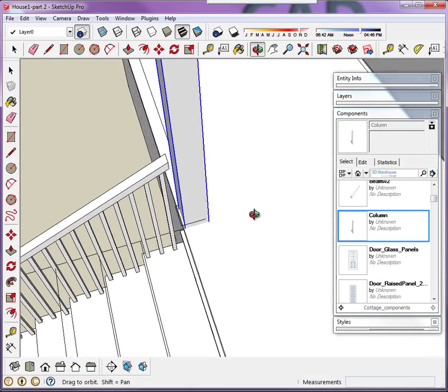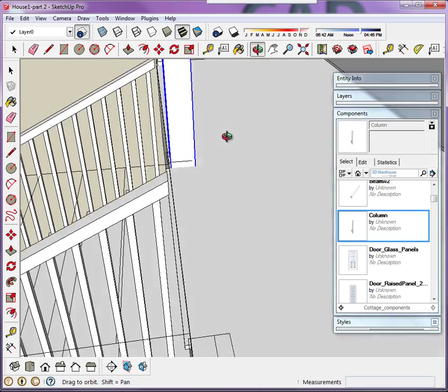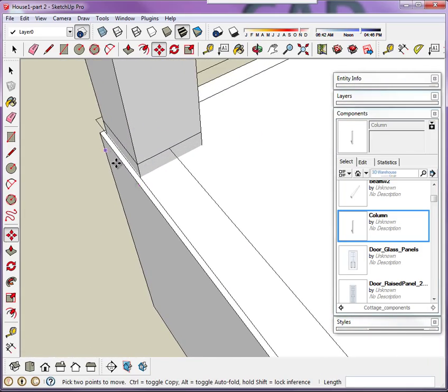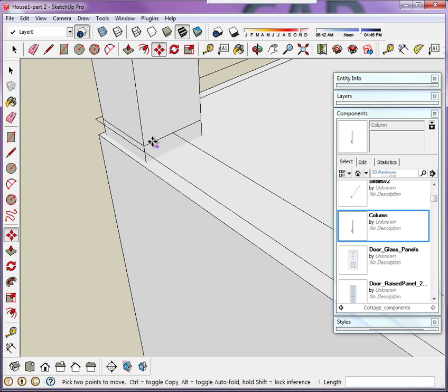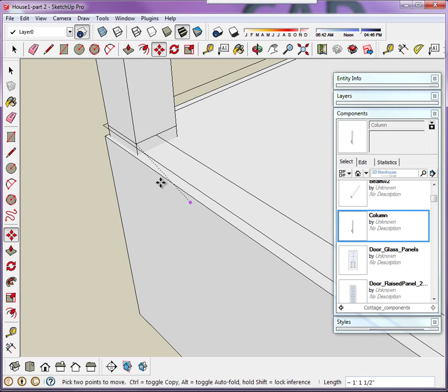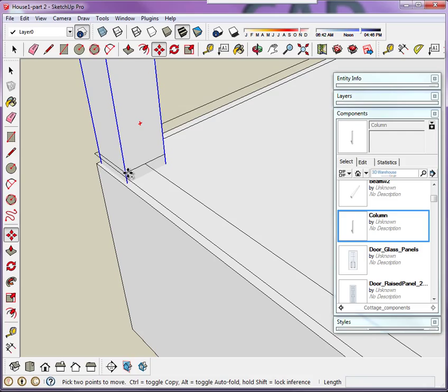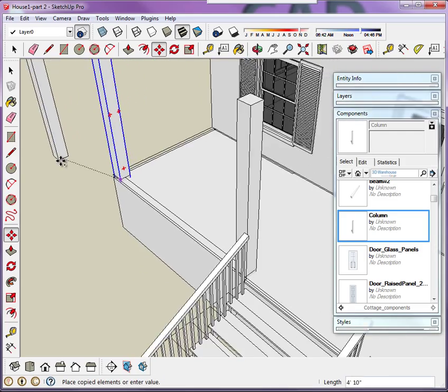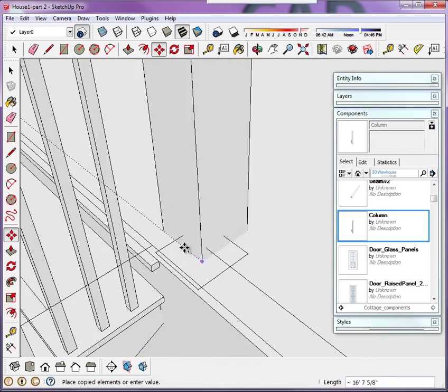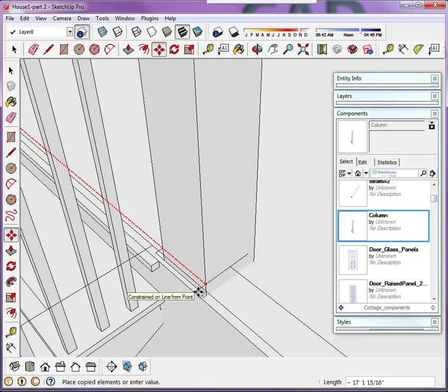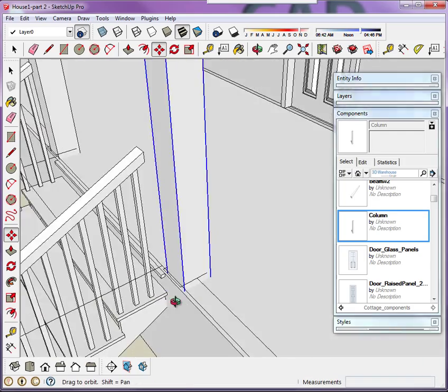That looked like it shifted a little bit. Just make sure that they're aligned with the first one that you put in. All right? See how it's aligned here? You can use one corner together with, let's select this one, use move, and then tap control. Okay, see how I'm making a copy? Come over here to this side. Notice how I snap to the x-axis, use shift, and then I could just snap to that corner right there.